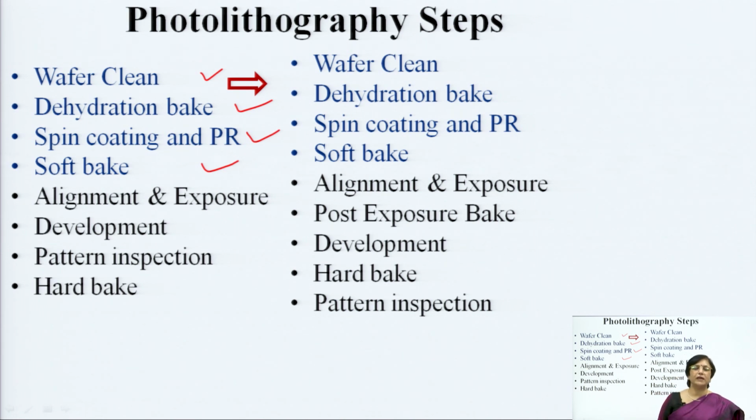Now, this soft baking is basically to ensure that the photoresist is properly layered onto the wafer, and that its adhesivity, or sticking ability, is good.